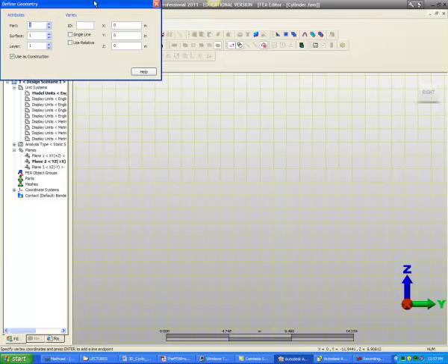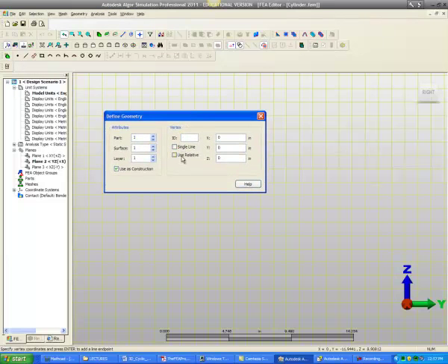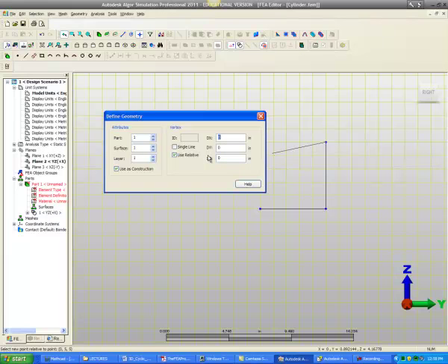I'm going to go ahead and create a line. Some of this will look quite similar to what we've been using. I'm going to start out at 0, 0. Now, if you recall, the pressure vessel we looked at had an inner radius of 5 inches and an outer radius of 10 inches. So I'm going to put my next point 5 inches in the Y direction, and then I'm going to take as a slice, let's say, let's make it 5 inches high for height on it. So that would be DZ is 5 inches.